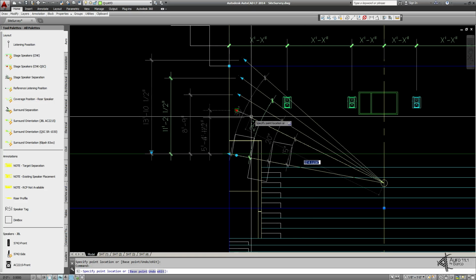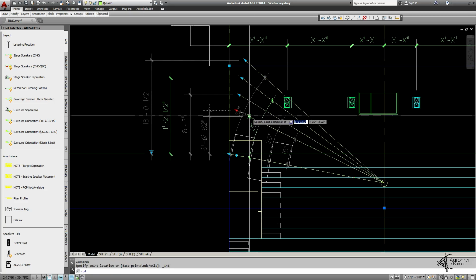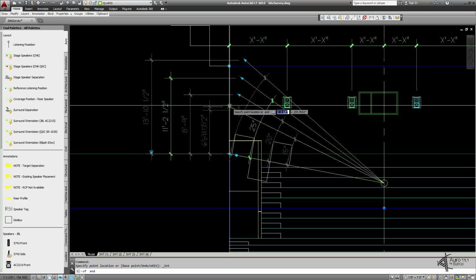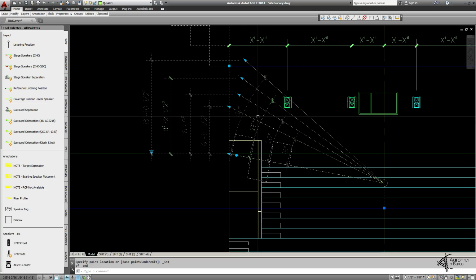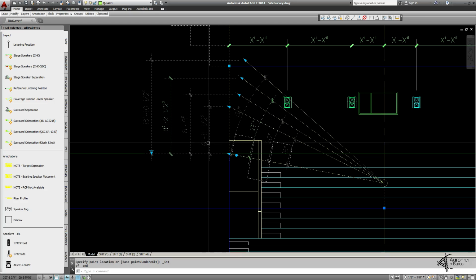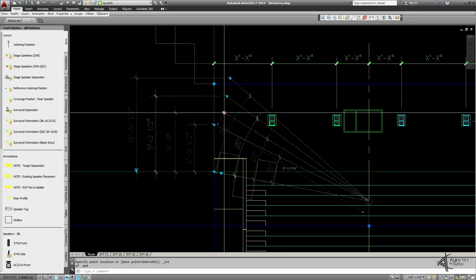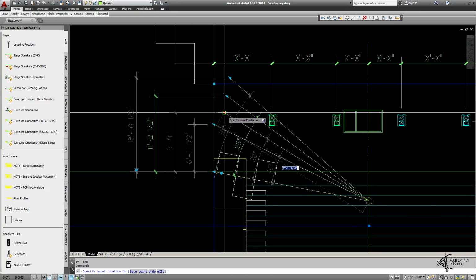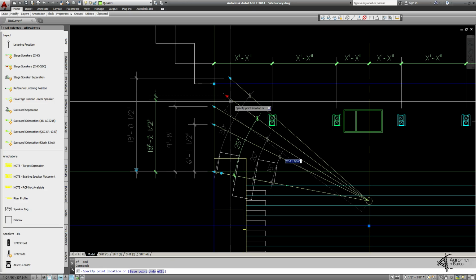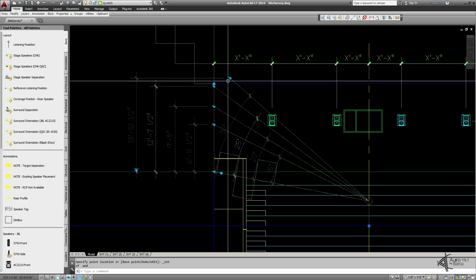So if we do this and then just do an intersection grip, it turns into an apparent intersection because we're going to pick this line so you can see the little dots after the X there, and then pick this line so it moves the end of that right up there to where our wall is, and that dimension is the number that we would hit at that angle. So then I pick up this grip and do the apparent intersection of those, etc., up through these.